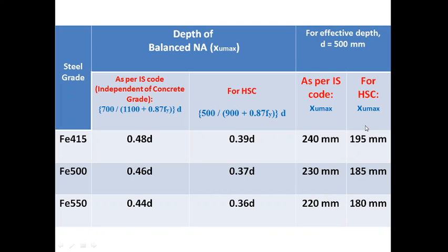There is a scope for research in this area, but I am not coming to any conclusion with this discussion, because whether it is 0.0035, 0.0025 or any other strain value, these strain values are obtained by conducting experiments on plain concrete elements in the lab. In RCC we don't use plain concrete, we use concrete plus steel.